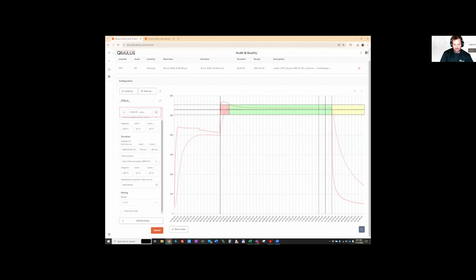Let me make one point here, please. Keep in mind that you may have maybe 7 thermocouples and all have to be in band already to start the timer. You can easily create your own signals. I think we showed that last time in the webinar briefly. So you can create your own sensors, and the sensor could be named minimum thermocouple reading of zone 1, or thermocouple 1 to 6, for example. With this signal in hand, you could also trigger it. So it's possible, definitely.